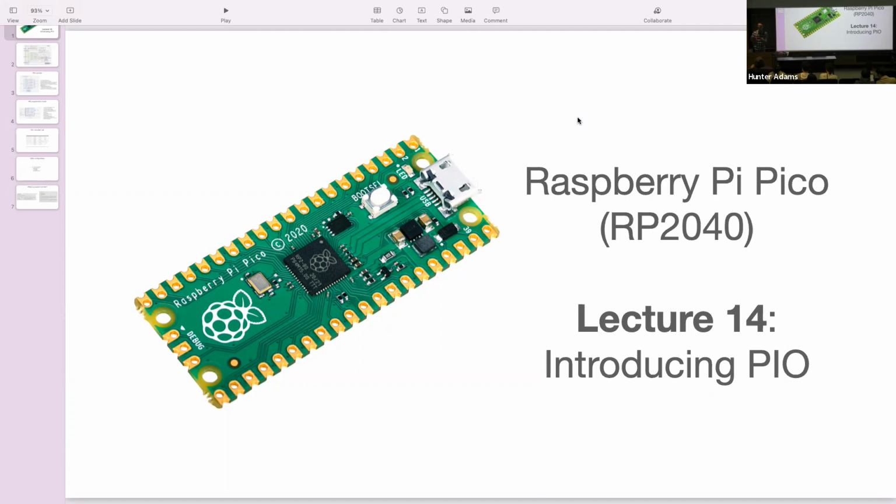If you just type 0.2 and you don't do float to fix of 0.2, I believe it does an implicit cast to a signed int, and it just makes it 0. So the bug associated with forgetting to do a float to fix on your turn factor is you start the animation and the Boids just fly off the screen and never come home, because your turn factor is effectively 0. So they leave the margin, you start applying the turn factor, but you're adding and subtracting 0 from each of their velocities, so they just keep on flying away.